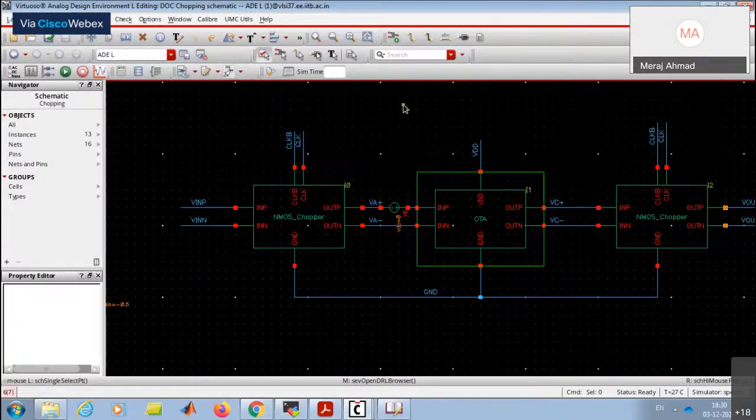If the input from the sensor is a very low current, which type of amplifier is preferred? If you want current sensing, then a transimpedance amplifier is a good option, which converts current into voltage, and they are using chopping techniques. If you see some latest papers, they have this to reduce the noise. I think TIA is a very good option.